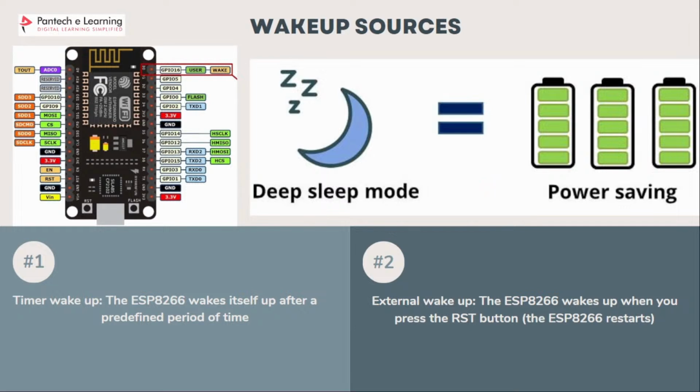Everything is off except the real-time clock, which is how the ESP8266 keeps track of time. This is the most power efficient option, and the ESP chip only draws approximately 20 microamperes. However, if you use a full featured development board with a built-in programmer, LEDs and so on, you won't be able to achieve such a low power state.